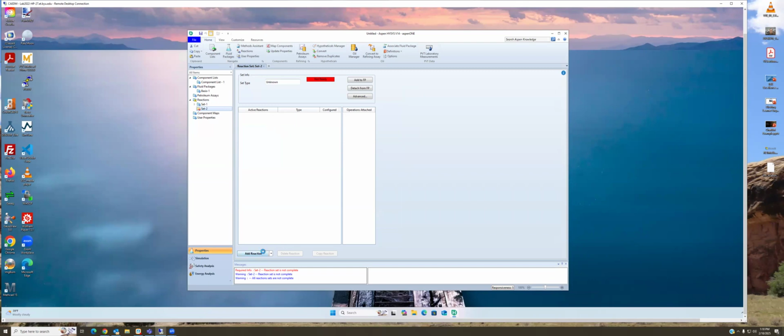And remember, we said when we were talking about this reaction that we were going to be able to assume that the ketene is completely reacted away to the acetic anhydride, provided we feed sufficient of the other reactant, the acetic acid. And we said if we have a 2-to-1 feed ratio, acid to ketene, that the ketene will all be consumed. Well, that will give us the information we need to do this reaction on the basis of a conversion reaction, which also means we are going to use a conversion reactor.